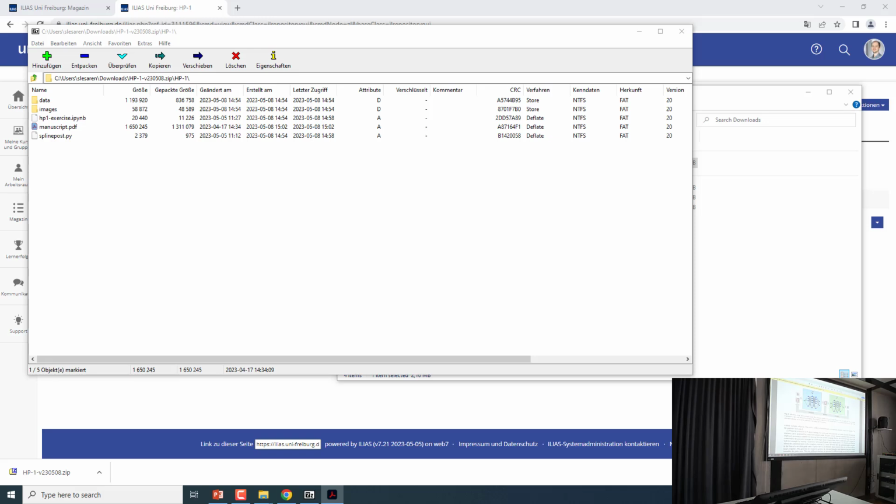So the idea, along the line of variational encoders and GANs, was to add an additional parameter. We say, okay, we don't want only to get the specific Poisson ratio, we want our curve, our unit cell, to look similar to another one. So we add what we call a guide curve. We not only want the Poisson ratio to match, but we also would like to have some preferences in the shape selection.